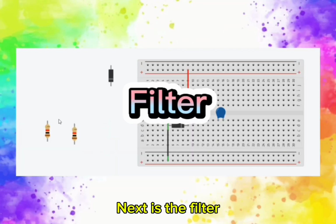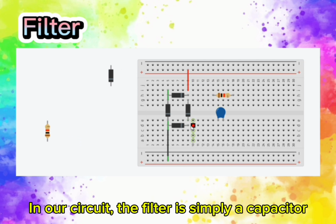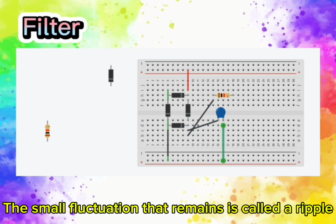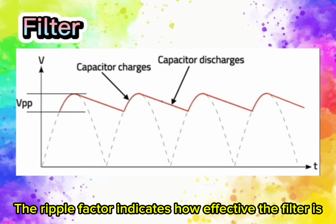Next is the filter. Its role is to reduce the variation in the rectified voltage. In our circuit, the filter is simply a capacitor connected between the rectified output and the ground. This helps to smooth out the voltage. The small fluctuation that remains is called a ripple. The ripple factor indicates how effective the filter is.